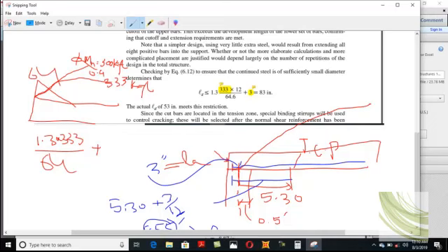Now you need to recall your lecture number 11, I think, where I explained these points: whenever you have a point of inflection, the moment becomes zero. You need to extend the bar for a distance of LA, and that LA here we extend from the zero moment point up to a distance of 3 inches. So therefore 3 inches added.